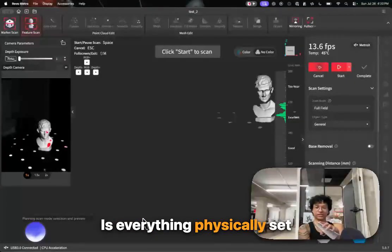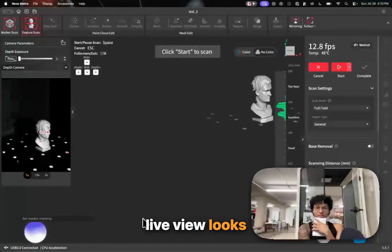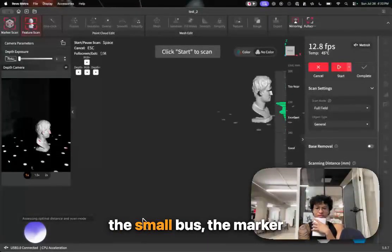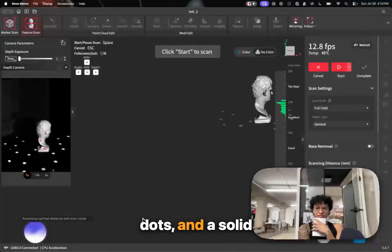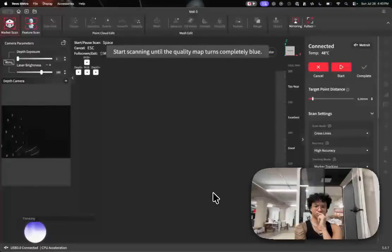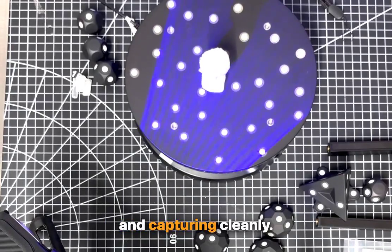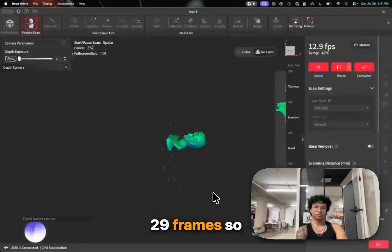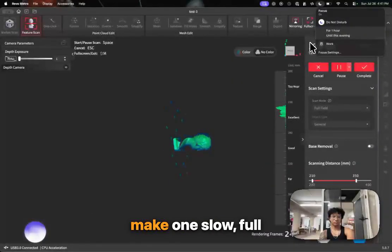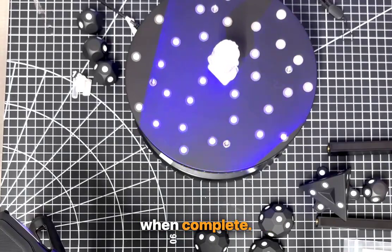Is everything physically set up right? The live view looks good. I see the small bust, the marker dots, and a solid distance reading. I'm setting up feature scan with full field, high accuracy, and automatic depth exposure for this test. Feature tracking is locked and capturing cleanly. 29 frames so far. Let it make one slow full rotation and I'll stop it when complete.